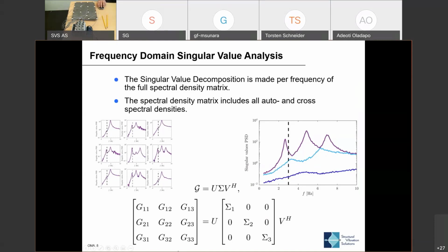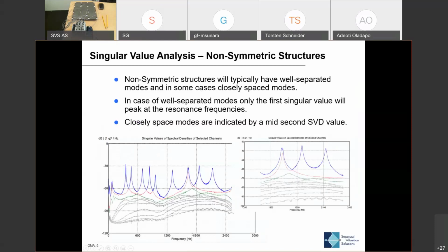If we go a little bit further here, there are different things we can see in this diagram. That's why I like to emphasize a little bit about this today. Because the first thing you can do is take a look at this structure here. This one is a rectangular plate. That means that it has some bending this way and some bending this way, but it will not happen at the same frequency normally because of the difference in the two sizes.